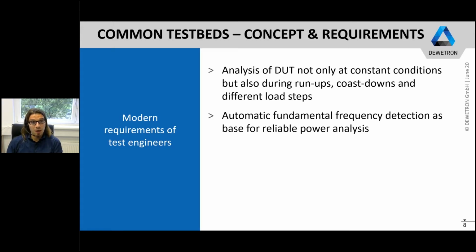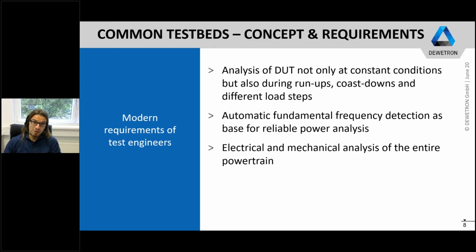For a reliable power analysis during these conditions, the power analyzer needs to provide a possibility to automatically detect the fundamental frequency of the system for analyzing the power accurately and for determining the power parameters. And as I also said on the previous slide, you don't only want to analyze the device under test in the electrical, but also in the mechanical domain.